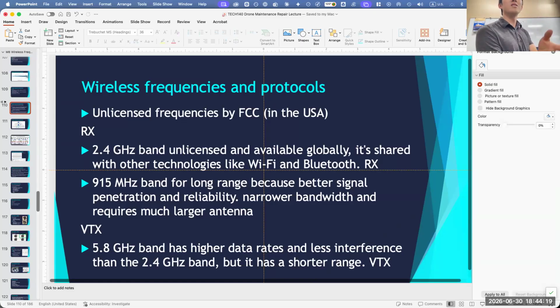Do you guys have a ham radio license? You don't need one to use your phone, right? Because we're using unlicensed frequency. As a result, though, very crowded. A lot of devices are using these frequencies. It's not to say they're exactly on 2.40000. It's a window, like 2.3 to 2.5. So you can have a device on 2.351 and then 2.362 and it'll be okay, assuming other factors are also considered in terms of power output and your bandwidth and things like that.